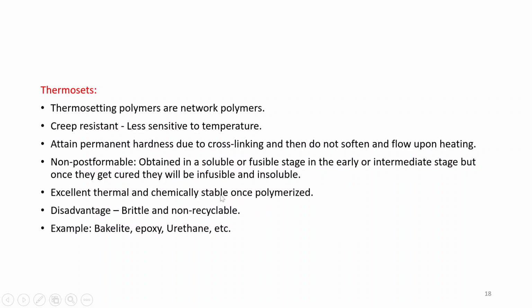So compared to thermoplastics and even metals, they show higher chemical stability. And thermal stability is poor compared to metals but better compared to thermoplastics. These are also brittle compared to thermoplastics. Thermoplastics show higher ductility compared to thermosets, and also these are non-recyclable.